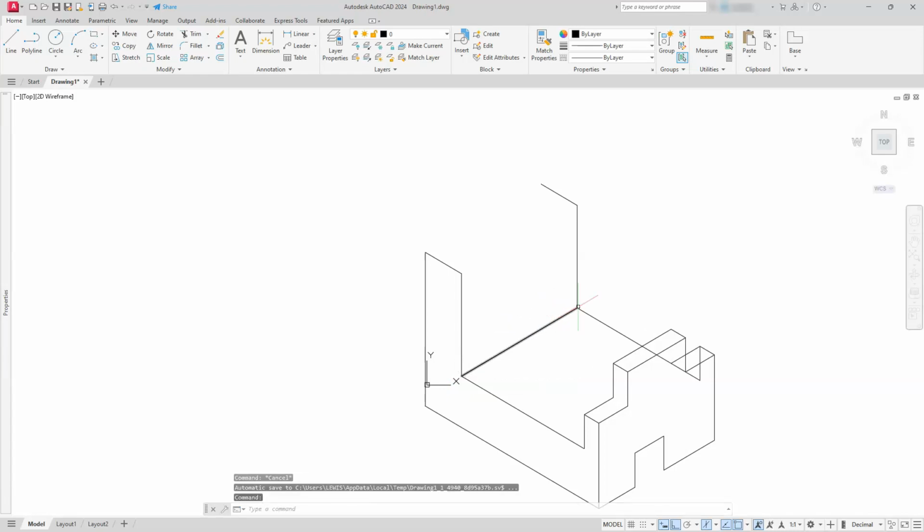And that time I just used the line command, so that's another way you can do it, is just hit L, enter. And I can go ahead and create these and just copy this around here. So instead of using the copy command, I'll also show you something else with grips. So I want to copy this line, so I'm just going to select here. The space bar, I see the word move. I'll type in C, enter. And then I'll just click that endpoint and that endpoint.